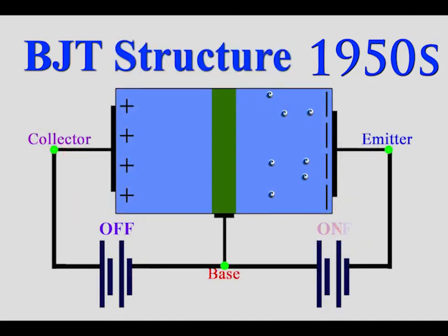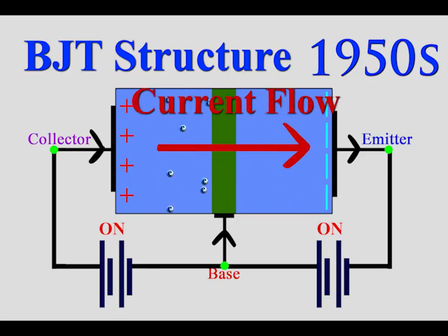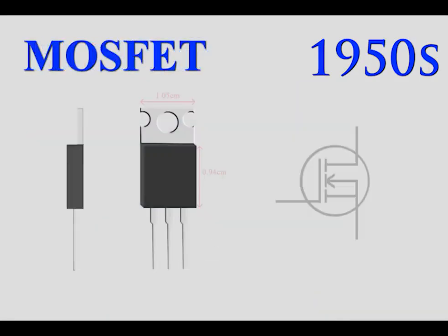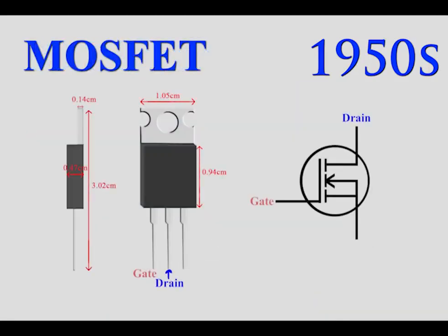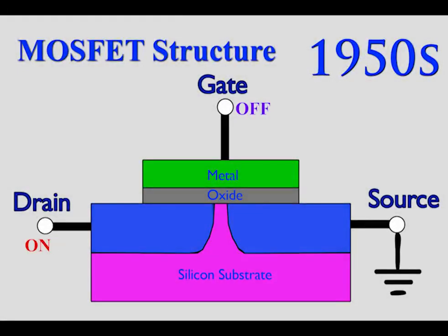During the circuit completion, the small amount of voltage or current applied to the base emitter terminal can cause current flow between the collector and emitter. BJTs can be used as high-voltage controlled current sources, current-controlled current sources, or a current amplifier. On the other hand, MOSFET has drain, gate, and source. Instead of applying current into gate, MOSFET relied on voltage to control the switching application between drain and source.